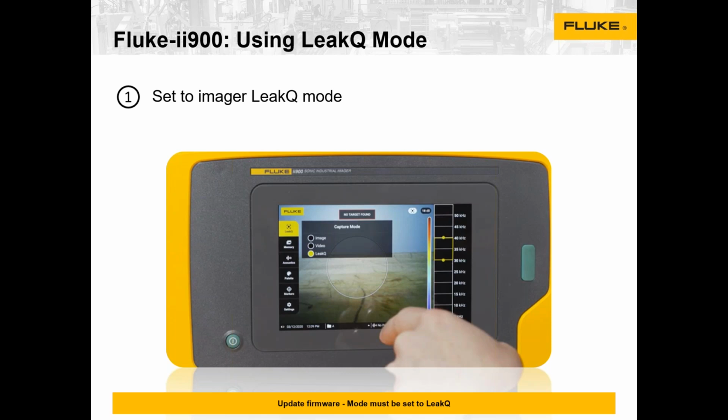So you put the imager in leak queue mode, and what you're going to see that's different than capturing images in regular mode is this circle popping up in the center of the screen, and you're also going to see that prompt along the top that says no target found. So now the II-900 is looking for a leak, but it's looking for it in that specific area. You'll know you're in leak queue mode if you've got that circle in the center of the screen and that display of no target found.